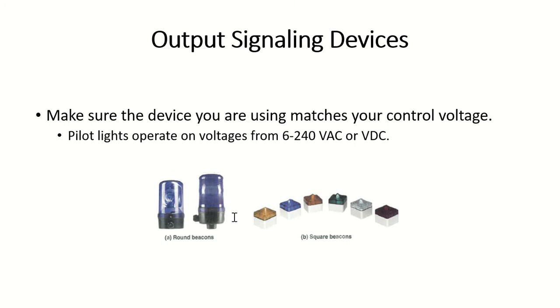The most important thing that you guys should be paying attention to when you're wiring these devices up is the control voltage that they use or consume. Each one of these, again, you can order for different voltages depending on what your system uses. Common systems are 24 volts AC, 24 volts DC. In our classroom, we're going to use 120 volt AC control.